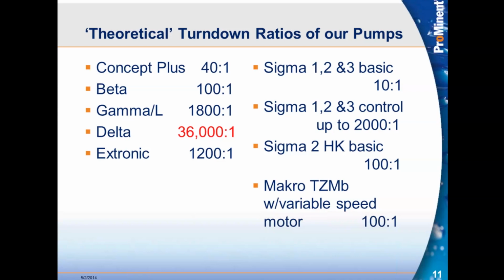So now, where in other scenarios we have one dose and 60 minutes worth of water goes by before we have another dose, we would have one dose and 57 minutes worth of water would go by, or process would go by, until we have another stroke. So it's a little bit better, but that's still a very long time without any chemical going into the process. Most likely, that's not realistic for us.